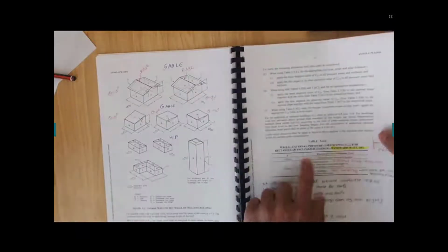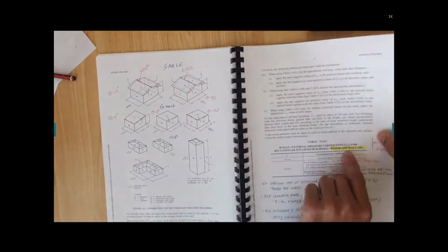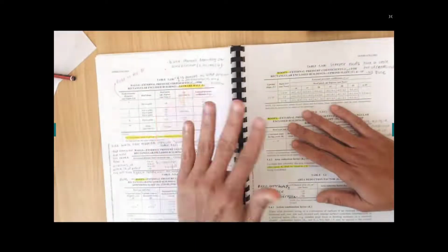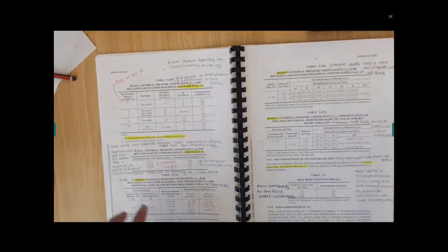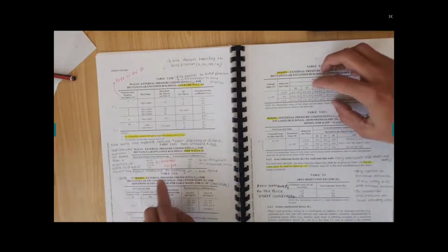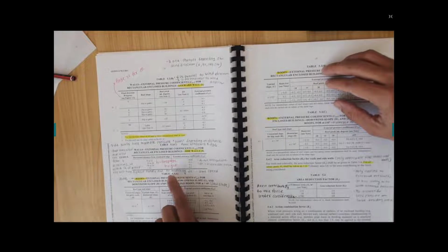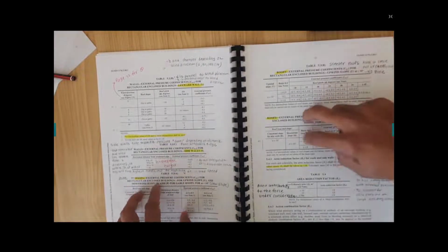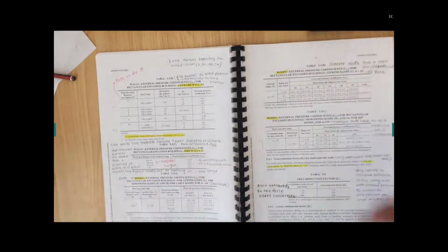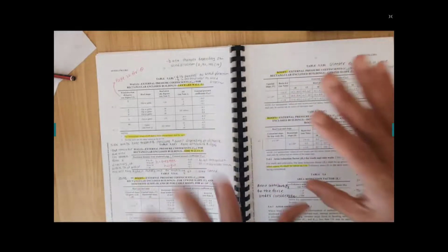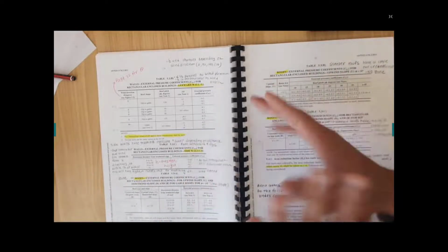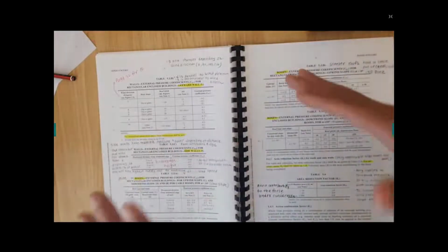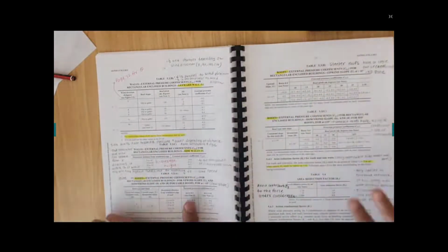So basically 5.2 is dedicated to walls: windward wall, leeward wall and side wall. There are another 3 tables, 5.3a, 5.3b and 5.3c, for the roof. I will tell you how you can distinguish between these 3 tables. So it's clear: if someone says calculate the CPE for me, you have 6 tables to deal with, 3 tables for wall and 3 tables for roof.